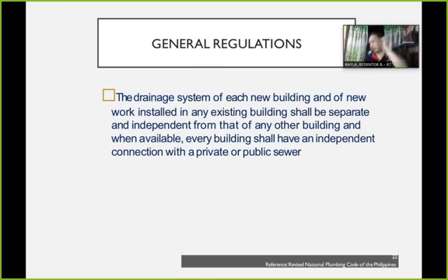But in this one, you can have a common line in order to receive all the different types of discharges from different buildings. You can make a network connection. At least you have tried designing this. You have to consider the scouring or slope requirement, as well as the different distances of manholes and the invert level, to connect to the public sewer line.